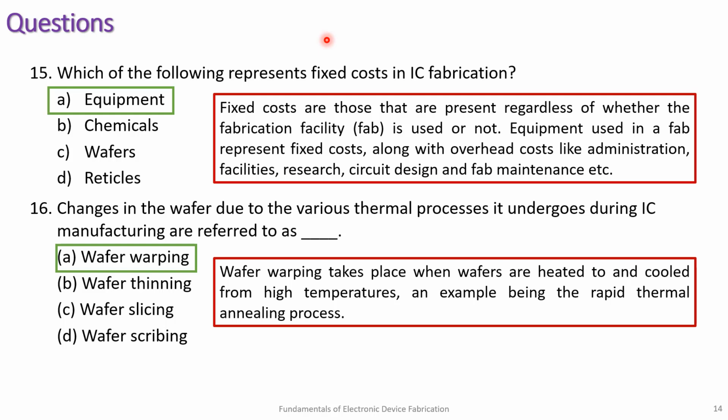No, annealing is a controlled one. Whatever you told is quenching, a sudden process. The controlled one is annealing. It depends: in steel, when we study, sometimes you want something known as martensite, and in that case you have to do quenching to get martensite. It will depend on your final requirement. For a wafer, it should be a very controlled process.